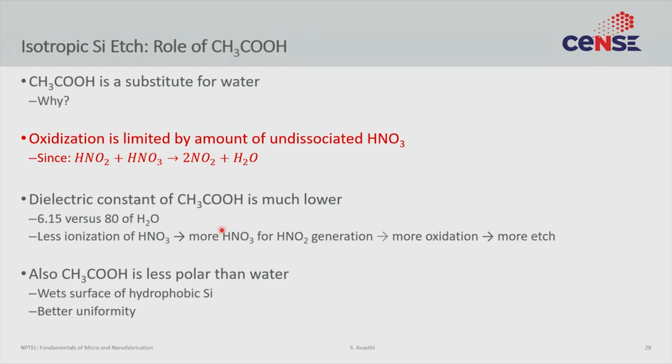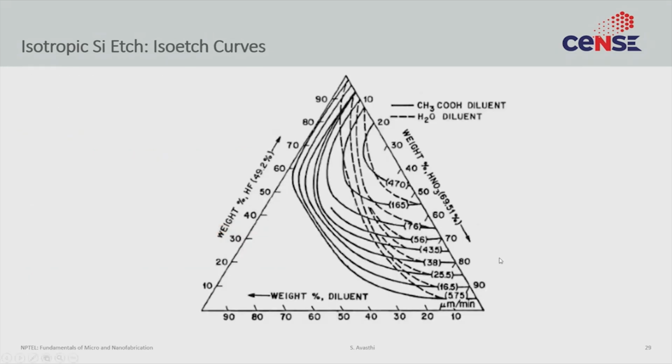So it turns out acetic acid is one such solvent where it wets the exposed silicon better than water does. So those two reasons are why you want to do this whole process in acetic acid and water. Okay, moving on.